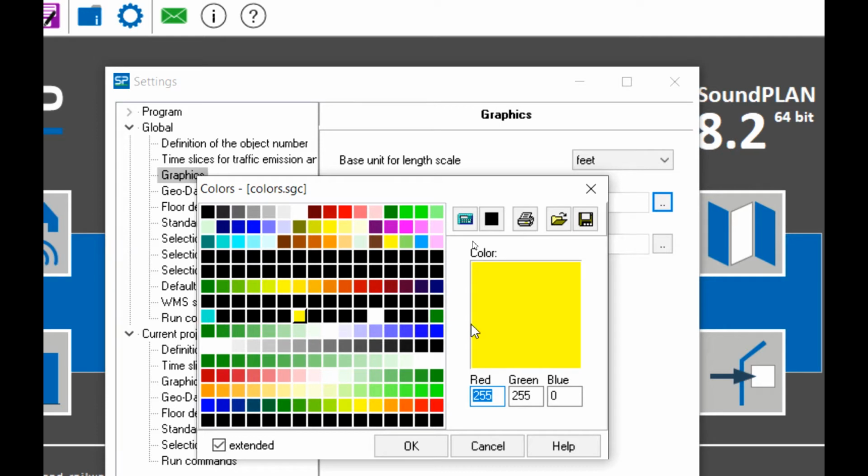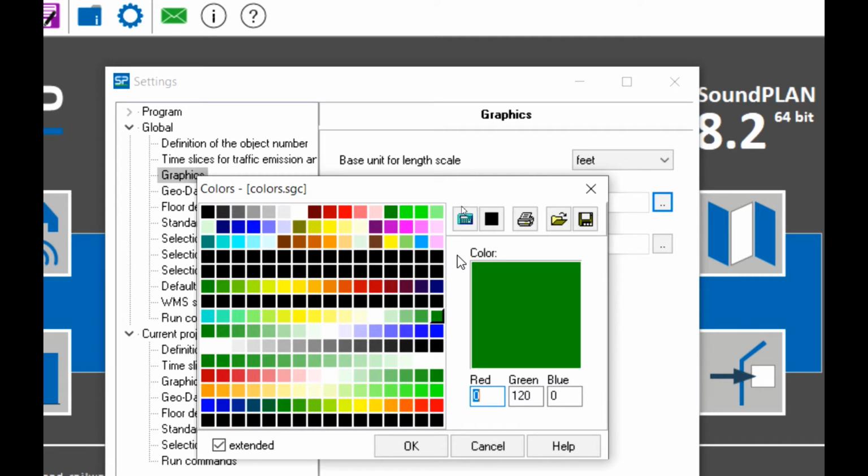Now we have a total of four colored markers, and we let the program interpolate between them. I can go to the yellow here and click on interpolate color values between the yellow and the turquoise. It will always interpolate from right to left. Here, if I click, this is the point that is selected. I click on that, so it interpolates to the left. I can go to the white, interpolate to the yellow, go to green, interpolate to the white. These are some of the ways of interpolating intermediate colors.